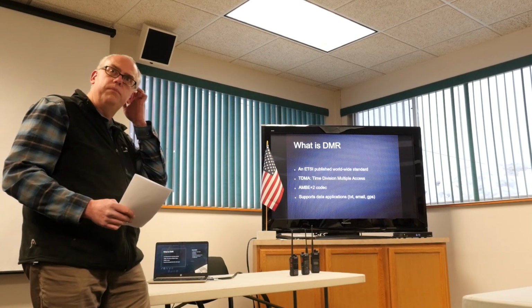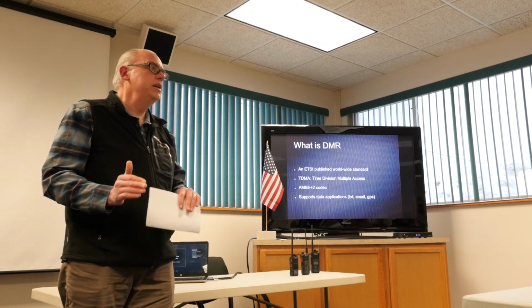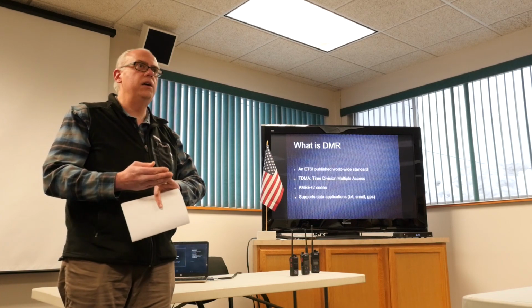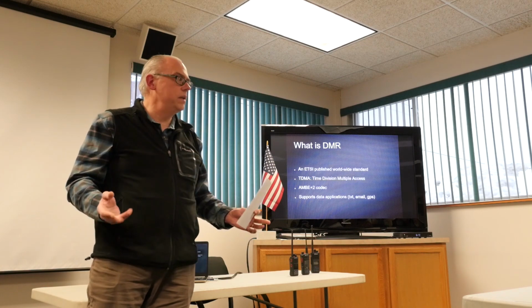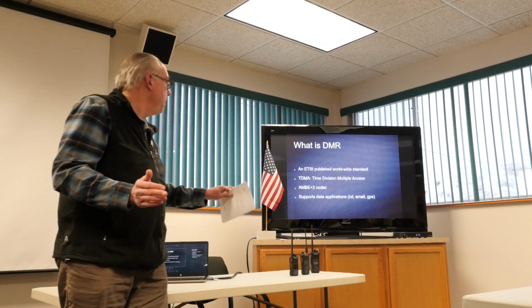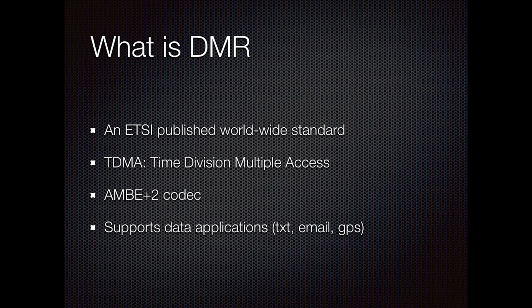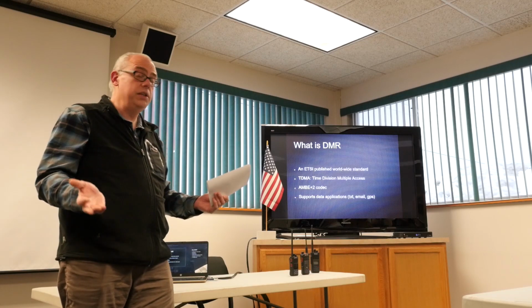It uses a mode called TDMA, which is time division multiple access, and that's really a differentiation between some of the other digital modes we see out in the amateur radio community, like D-Star or System Fusion. We'll talk a little bit more about that in a bit. It uses a digital codec called AMBE+2. So it's a very sophisticated digital codec, gives you very high quality digital audio, and also it supports data applications. You can also text, potentially email.